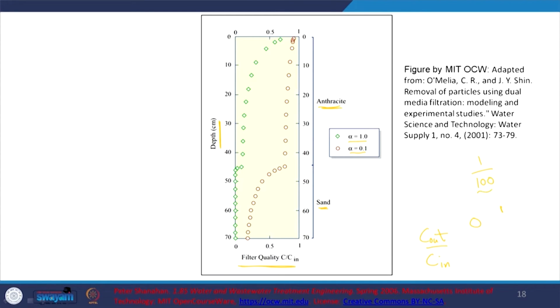So, what is the first aspect? Let us look at the case where chemistry has a role to play, so chemically treated. What do we have? We see that even at relatively low depths you do have some removal, but not a lot. The removal efficiency is relatively poor. But with depth the efficiency increases much more, and by the time it reaches the sand there is obviously a quantum increase, and the filter quality is remarkably good. So, you can choose your sizes and such accordingly.